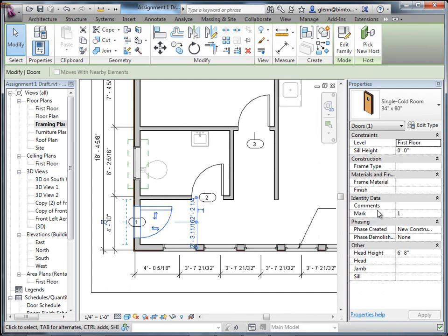And if you click on the door, you can actually see all these doors have a little ID number. It is the mark. There's an ID of individual things. That's called just the mark. There's something called a type mark, which is again a whole bunch of things that all have the same type. It's an identifier that gets the whole category as opposed to the individual instance. So I got these little door identifiers right now.